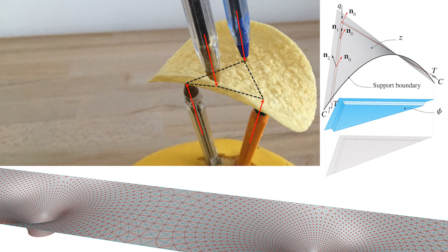Thus, a grid shell with members following asymptotic lines on a doubly curved surface will transfer loads only through axial forces along the members and, in theory, not rely on bending capacity. And we may use this fact to construct not only minimal surfaces carrying member stresses in tension, but also those carrying compressive stresses, or a combination of the two.